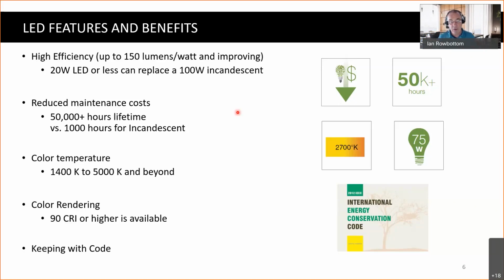And unlike the old incandescents, whose lifetime was rated, or even fluorescents, say I had a lamp that was rated for 1,000 hours, what that meant is if I had a sample of the lamps, 50% would be dead, completely non-functional at 1,000 hours. With LED, they just reduce their light output at the rated life. And we'll see that on a spec sheet, and I can explain that.